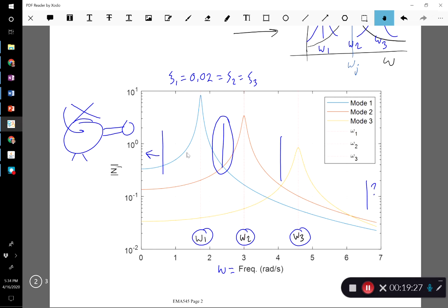And so what you saw there is that the speed of the engines came in line, say, with one of the modes, and so you get a large increase in the vibration amplitude and failure of the helicopter. Hopefully that makes sense now.